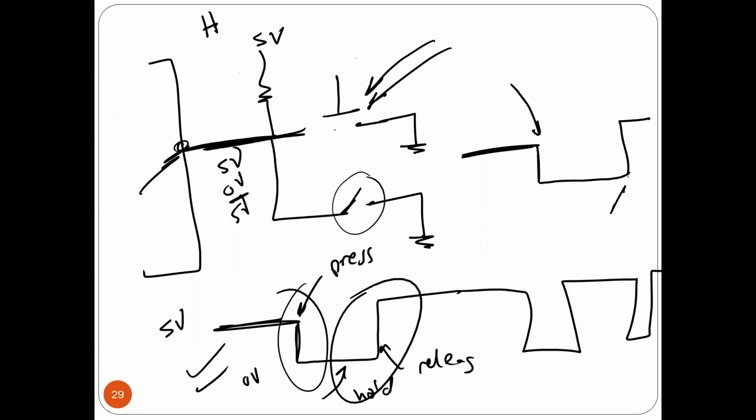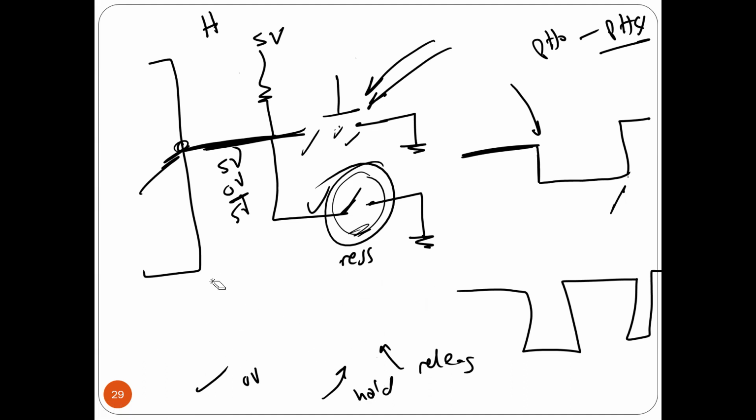So again, we have 4 switches, guys. These 4 switches are connected to PH0 to PH4. Also, they are connected to switches here. You have to use one of them at a time. You cannot use both of them at the same time. That's why if you want to use a push button, you have to make sure the switch is open, okay? Again, based on what I explained here, guys, it's just to make it very simple.